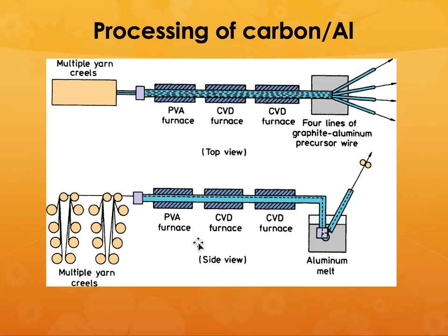result in aluminum carbide, Al4C3, which actually is strong at room temperature, but over a period of time it starts becoming a powdery material. And so you will have a block of material that is very stable as soon as you make it, but over a period of time, say for example 6 months or a year, the whole block will just fall off into powder, which is not a good thing. So you have to protect the carbon fibers before you infiltrate them with the aluminum metal.